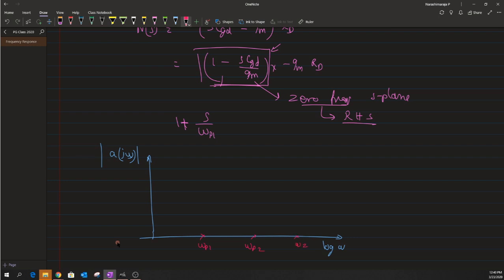and then omega z. Now, as said earlier, for each of these poles, I can roughly draw a linear approximation for the magnitude plot. There will be a degradation of gain at a rate of minus 20 dB per decade, and when we meet the second pole, this will further decay the gain by minus 40 dB per decade. Probably this will be much flatter compared to this.